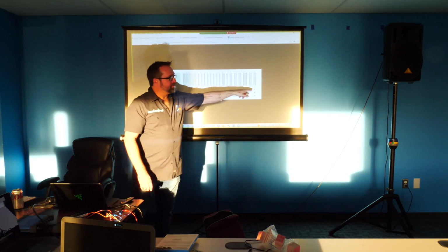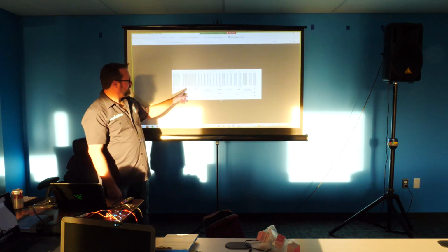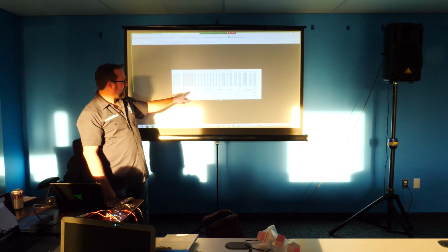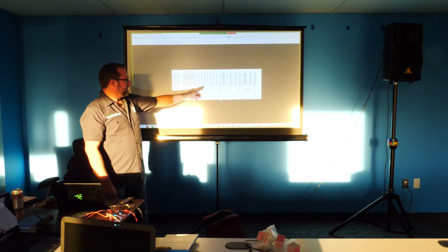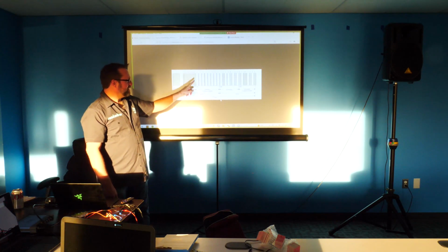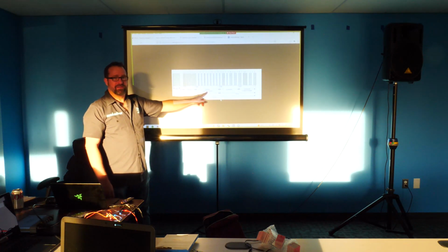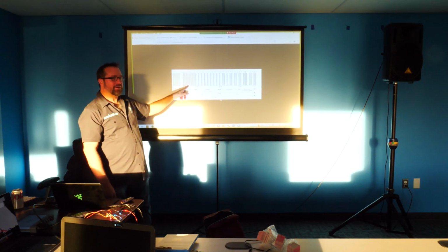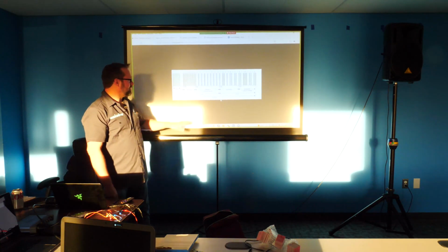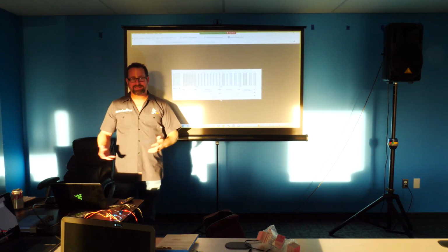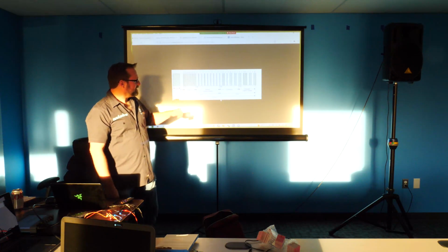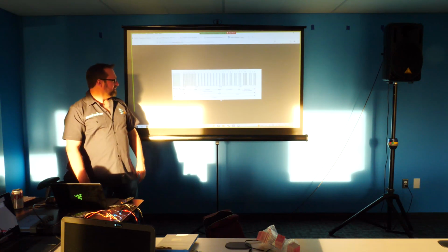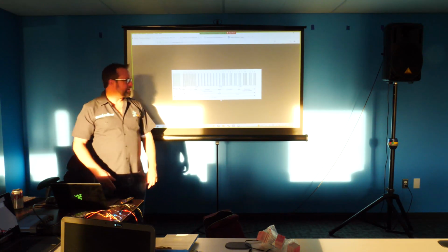It basically comes out to be a 32-bit number, and then it's actually only 2 bytes, because the address, the first part, is 8 bits, and the second part is the inverse of the first. So if this was 55, this would be AA. If this was 0, this is going to be FF. You don't really have to know any of that. That's just how it is. And the same thing with the command area. So there's really a 2-byte code, and we'll see in the software.